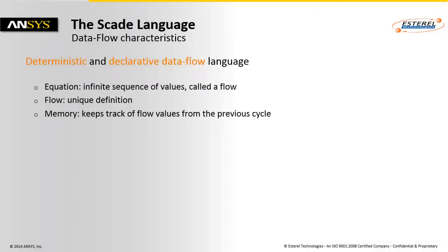The SCADE language is a deterministic and declarative data flow language. Thus, the order of equations does not matter, only the data dependencies. An equation defines an infinite sequence of values called a flow.